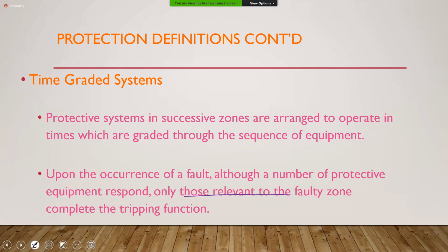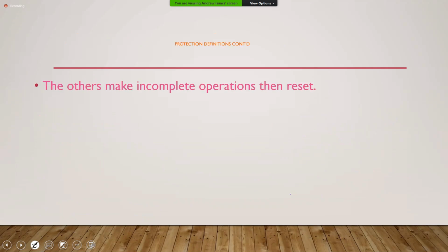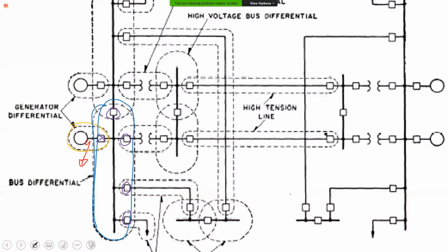However, if it doesn't trip fast enough, because it is now impacting another zone, the breakers in the other zone would then trip and isolate not only the generator, but if we go back here, we would have lost the fight, because if all those breakers trip, then this transformer would be out, this line will be out, that line will be out, it would separate from this section of the bus bar, right?